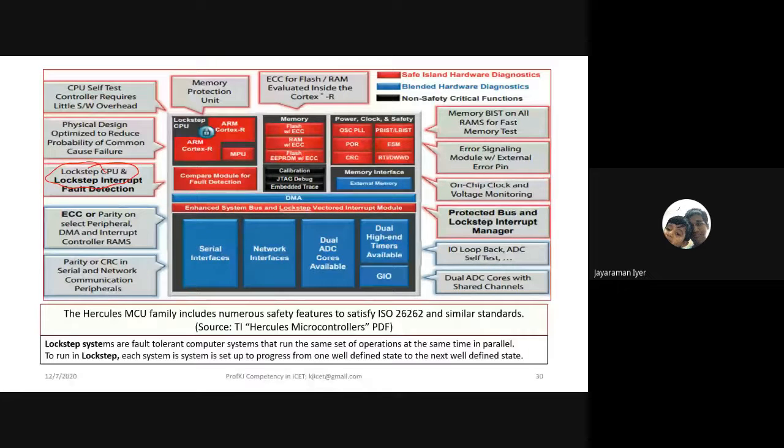That means what? Reliability is the probability that the system, service or product will function as per the design specification at the rated condition whenever it is called to perform. That's the definition. Now, if this has to work in that particular rated condition continuously, it may not give you the reliability that you want. So what do you do? You build a redundant system. That is one more parallel run, and these 2 parallel must work synchronously. That is what is called lockstep.